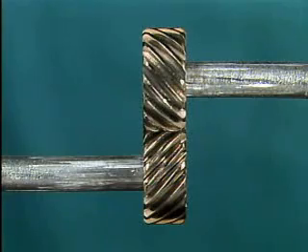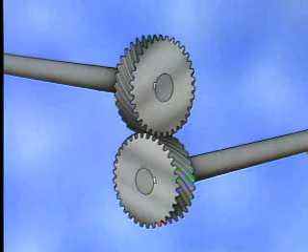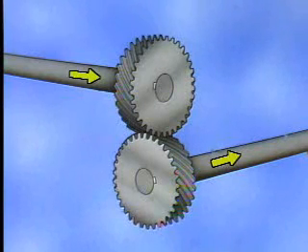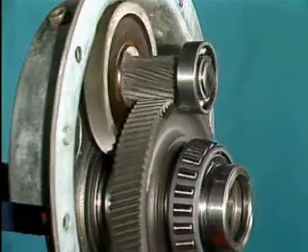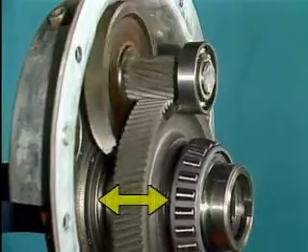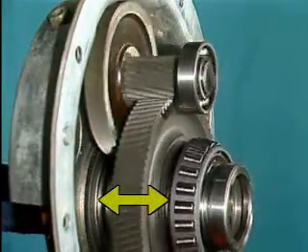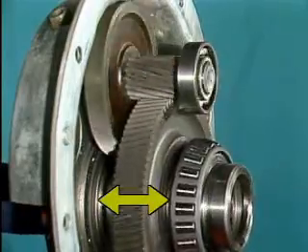Helical gears are normally used to transmit power from one parallel shaft to another. However, two helical gears may also be crossed to transmit power at 90 degrees. Helical gears are generally preferred over spur gears for high-speed operations because they can handle greater loads and they run smoother and quieter. Unfortunately, however, there is a problem associated with helical gears that needs to be addressed when these gears are used. The problem is that as helical gear teeth mesh, an axial thrust is developed along the shafts that support the gears. In other words, the gear and shaft try to move sideways.